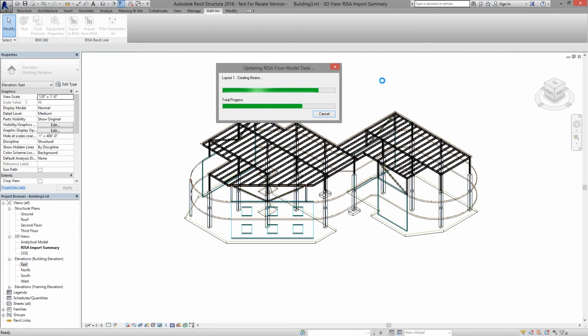We resized basically all of the steel. We resized the foundations and the concrete columns. I think the only things that really didn't change were the two-way slab thickness and that shaft opening. So we can expect a little bit of time spent running through here. This is just Revit making sure that everything is thoroughly connected to everything else. Once this import completes, we're going to get a report that will explain whether there are any problems bringing it in.